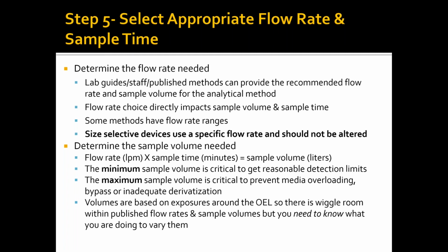So for certain compounds, and I've run into this with methyl methacrylate, it has a very low sample volume on those tubes. And sometimes you need to do 2 to 4 samples to cover an 8-hour shift because the capacity of that tube is just so small. And you need to know that in advance so you order the right sampling media and that you follow the volumes that are specified in the method.